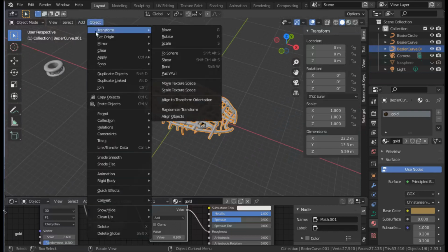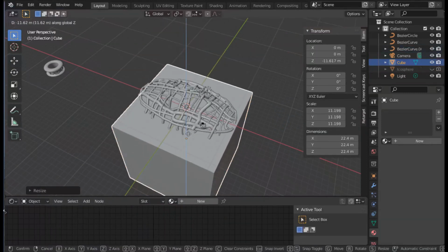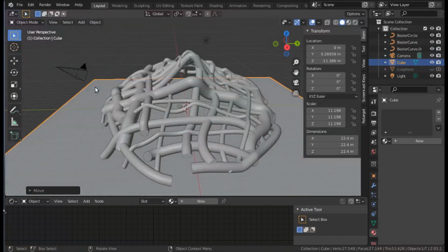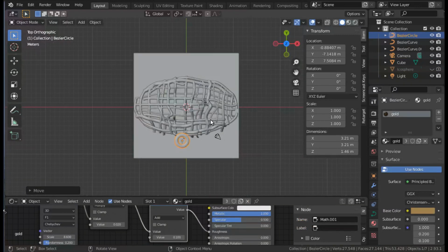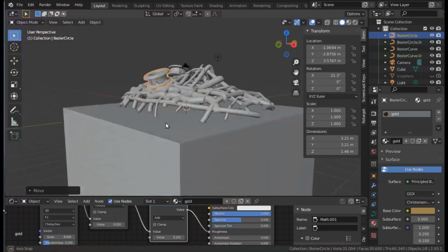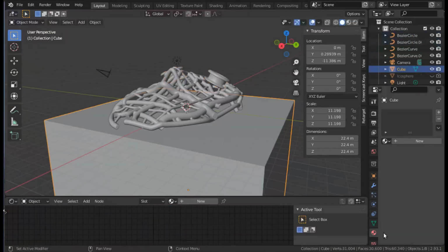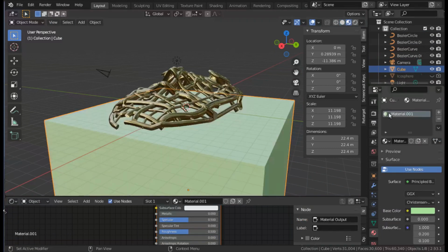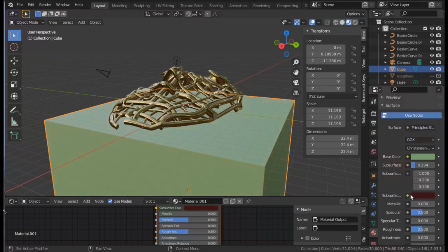When we're happy with the mask, we can create a plinth for it to stand on. We make a duplicate of the ring and have one for each eye, just as a slightly surreal thing. So I'm making it look like a kind of plastic covered plinth. We change the colour and make it look plasticky by adjusting the subsurface amount and subsurface colour and the roughness.